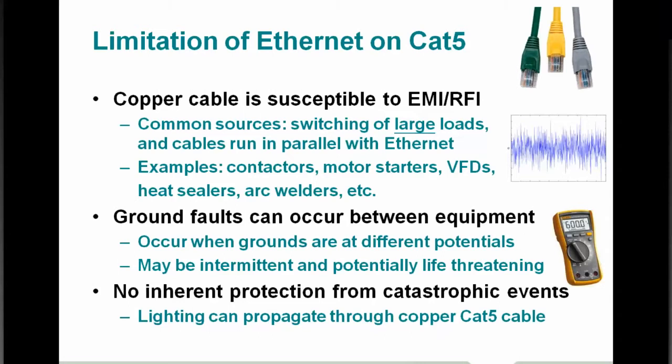If you've got a difference in ground potential and the connection between those two endpoints is via Ethernet, that can cause problems. Now, granted, there's some great design in the Ethernet standard, going back to when twisted pair cabling was introduced, but these can be significant issues, particularly in inter-building connections when you want to run Ethernet from one building to another.